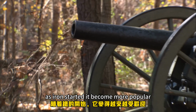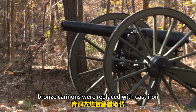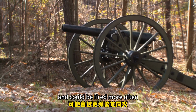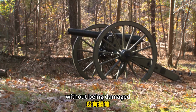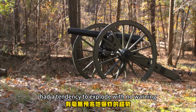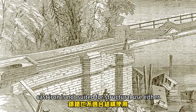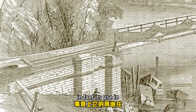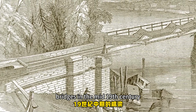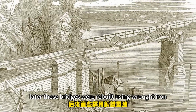As iron started to become more popular, more and more of the early bronze cannons were replaced with cast iron, as it was cheap to manufacture and could be fired more often without being damaged. But these material properties meant that cast iron cannons had a tendency to explode with no warning, making them dangerous to operate. Cast iron is not suited for structural use either. In fact, its use in bridges in the mid-19th century led to a series of bridge collapses. Later, these bridges were rebuilt using wrought iron.